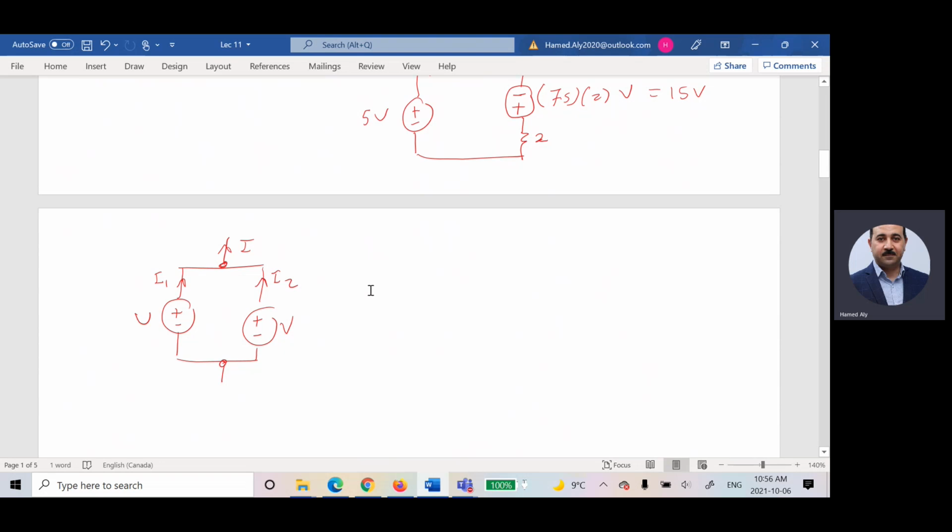And in the same way, connecting two sources in series, something like that. This guy, if it is I, this guy should be I. It shouldn't be different. But why am I connecting them in series? Because I would like to increase the generated voltage. So I have voltage across this guy and across this guy.